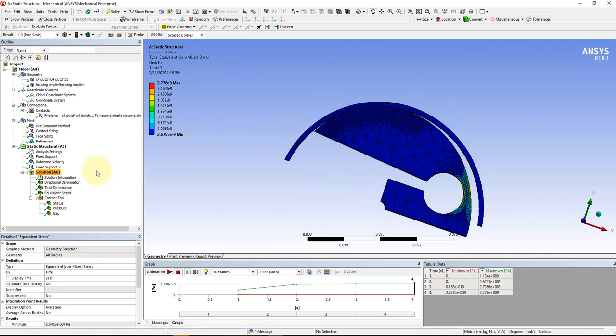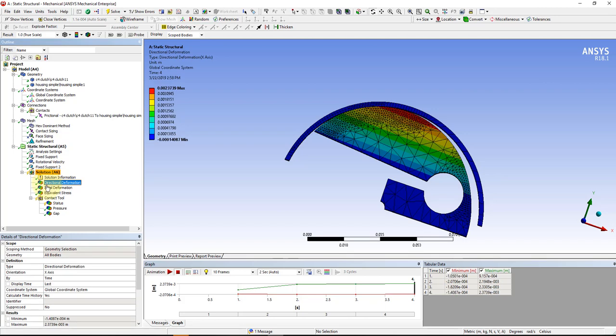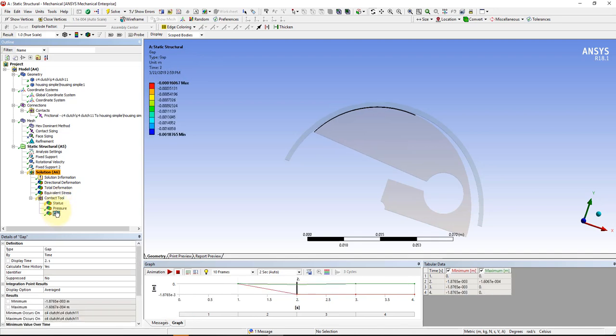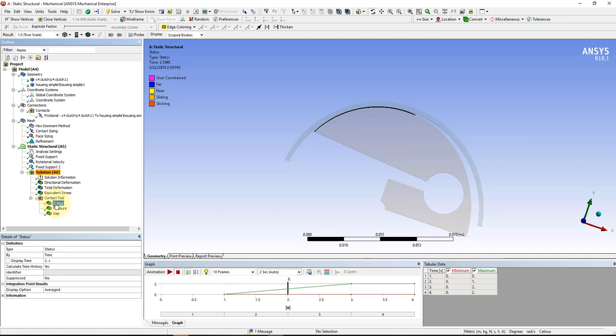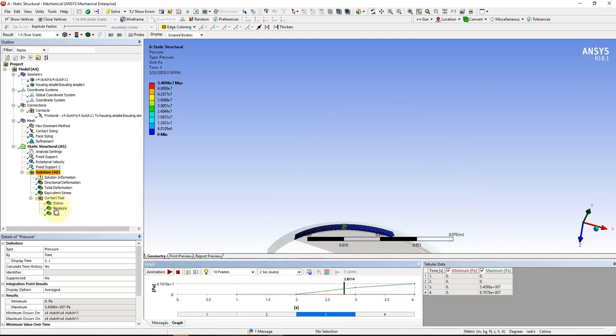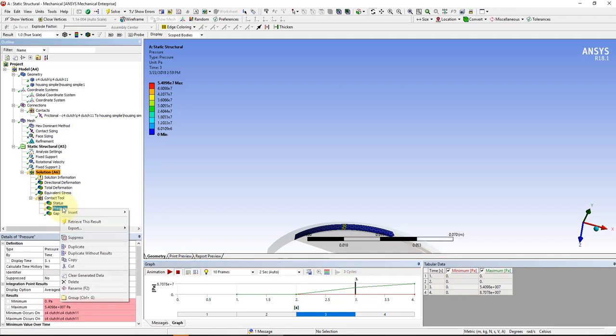Your challenge is to look and say, well, what is the maximum position here, the maximum load at which it begins to interfere and to touch. And so you could imagine that this contact status might be a good value. You could use any of these values, possibly with some amount of iteration to find about where that point is. Right? And let's see, retrieve that result. It's the same result we had before.